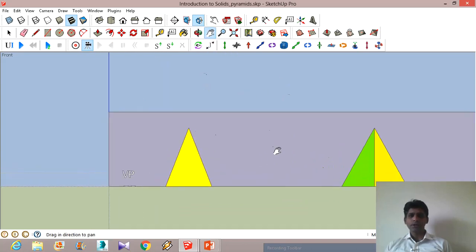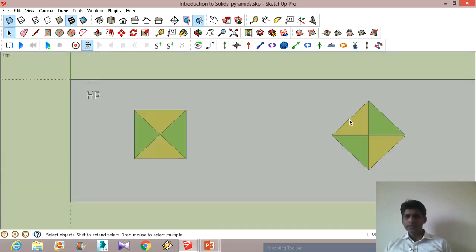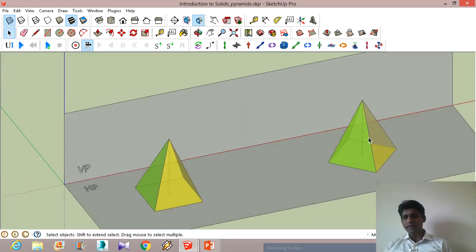Also observe the front view. We will concentrate only on this. In this view, I can see only one triangle, of course, and this line that you can see is the axis. But now when it is resting on a corner or on a slant edge, the orientation, that is the top view, is drawn like this, and the corresponding front view will appear like this. We can see the two triangular faces. This line is in fact this edge, but here you can see that there is no edge, so it is the axis. So we should note these things.